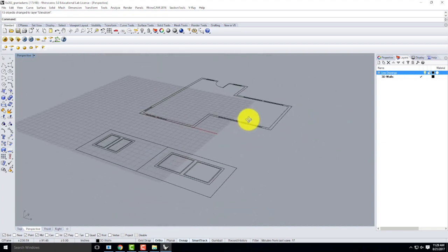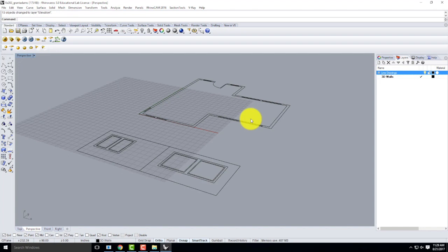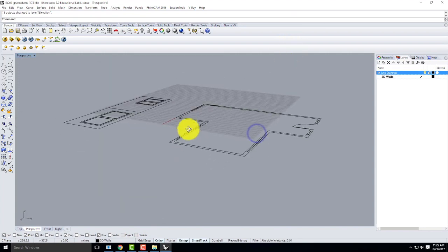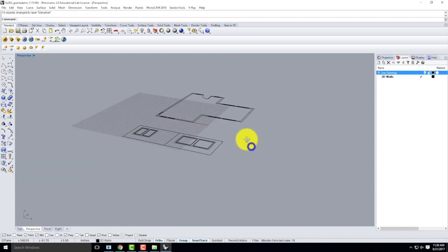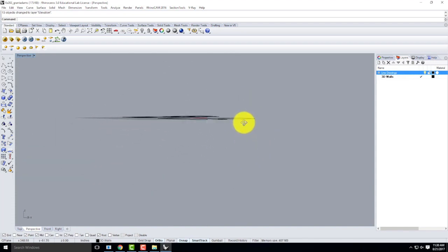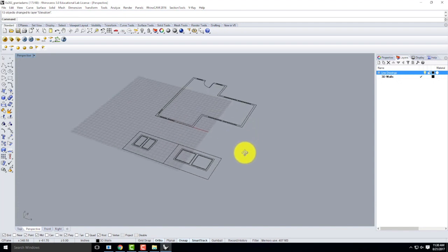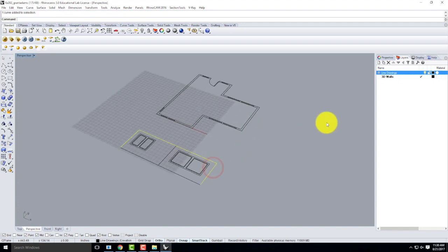Those of you that are comfortable with SketchUp, this is going to throw you off. And it'll throw you off backwards when you go back to SketchUp after working in Rhino, because they're different. So in our case, it's right click to orbit. There we go. Now, nothing is in 3 dimensions yet. If I get down here really flat, you see that it's all still flat. But I want to take this wall, or this south elevation on the elevation layer, and I want to get it standing up. Okay, so it's still lines, but I want to get that standing up.